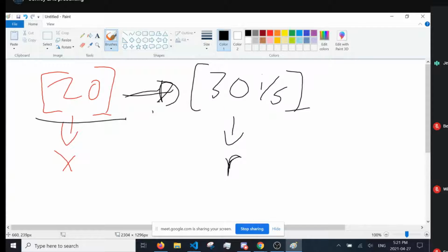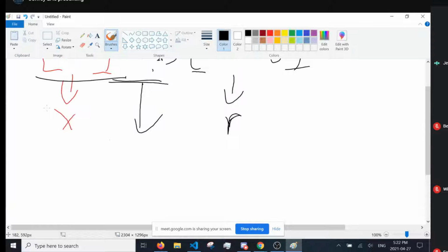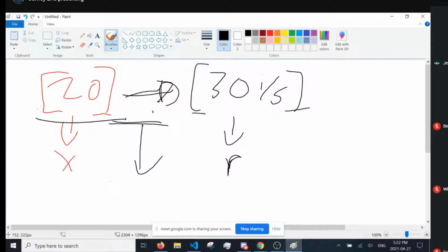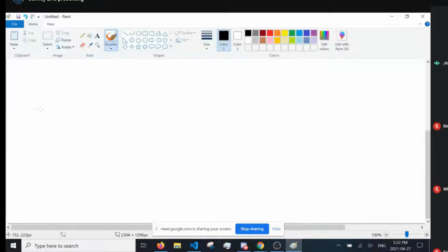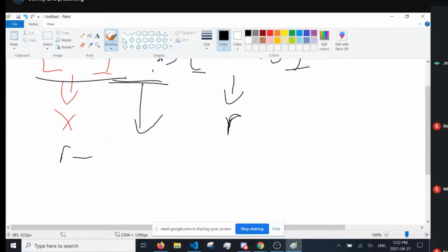The most fundamental subset of PID control is direct proportional control. First, we take our error in our current state by taking our reference state and subtracting our current state, which tells us what the discrepancy is. In this case, our reference minus our current state x is equal to 10 per second, and we label this our error.